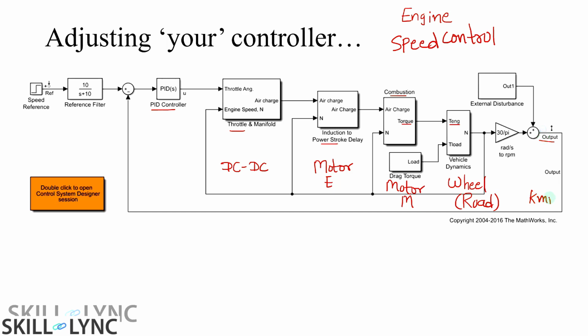So in this case, you want to control the duty cycle of a DC-DC converter, right? So this is a similar case where we want to analyze our system which is cascaded together, right? So we have an equation of a DC-DC converter where we can represent this block as V in and V out, or the ratio of VO to V in, and that is nothing but the duty cycle D, which is on time divided by total time T.